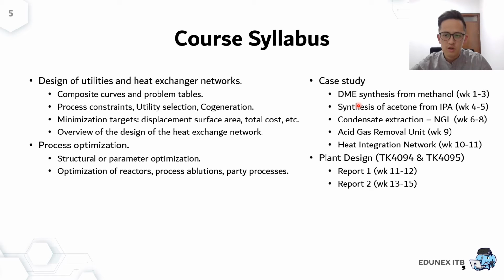We will talk about that in the first 3 weeks, starting from the basic concept, the basic process, how to make the PFD, and then how to start the simulation process, how to solve the heat and material balance using the simplified or the shortcut equipment, and then continue with the rigorous equipment design, such as the rigorous reactor, rigorous distillation, and then the heat exchanger optimization or heat integration.